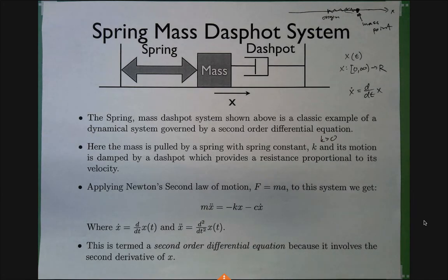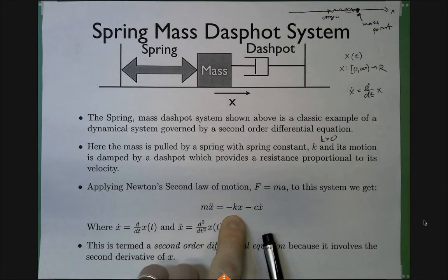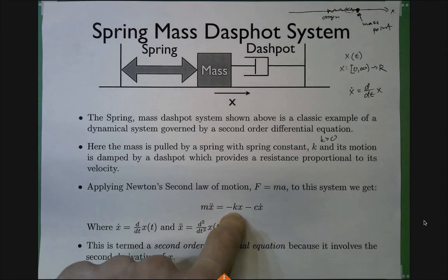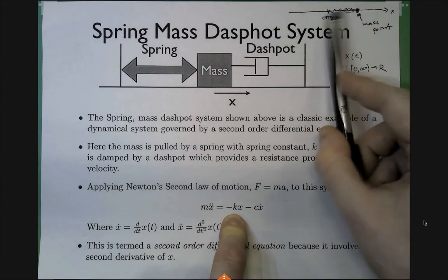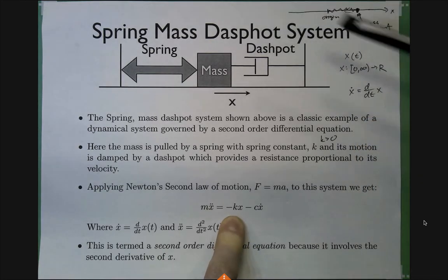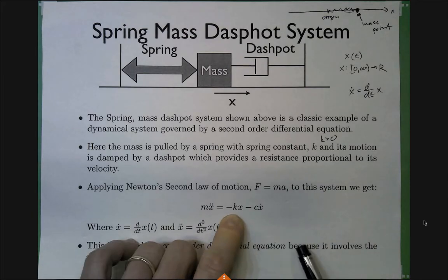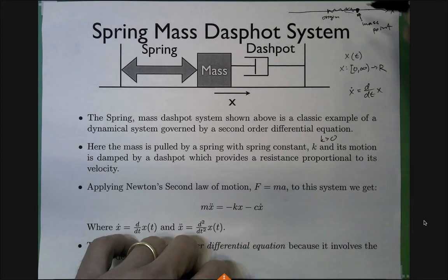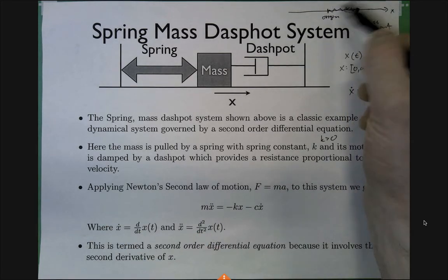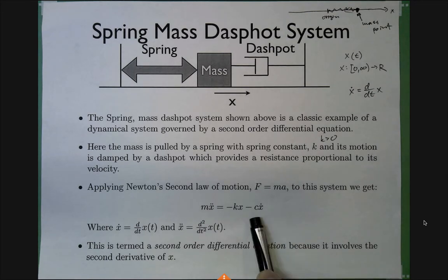And then what are the forces acting on my mass point? Well, the first one is the spring force. I said that the stiffness is K, so this force is linearly proportional to the stiffness. The higher the stiffness, the higher the force. If a steel spring is stretched to this length, then it will be pushing with much stronger force than a mushy spring. And it's pushing in the opposite direction. So if x has a positive value, then the force goes in the negative direction because it's pushing it back to the rest state. And c is the damping parameter, where x prime is the velocity.